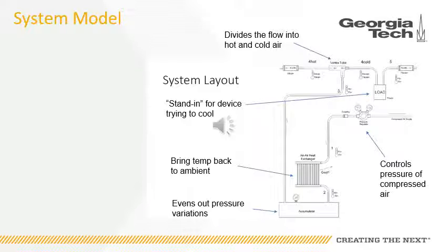The air then enters the vortex tube, which has 2 outputs, a hot output and a cold output. On the hot side, the hot output from the vortex tube is at ambient pressure but an elevated temperature and vents to the atmosphere. On the cold side, the cold output from the vortex tube feeds to an aluminum block with an internal heat exchanger. This allows the air to cool the block.